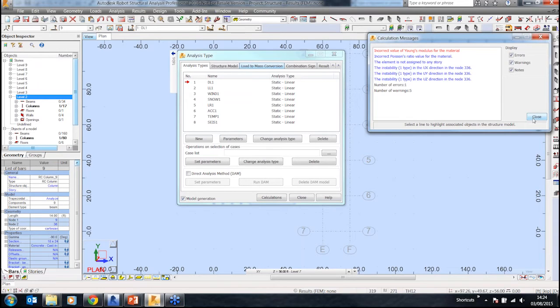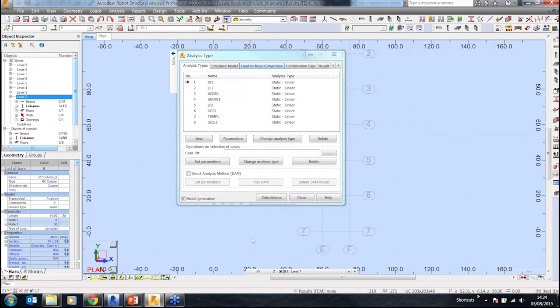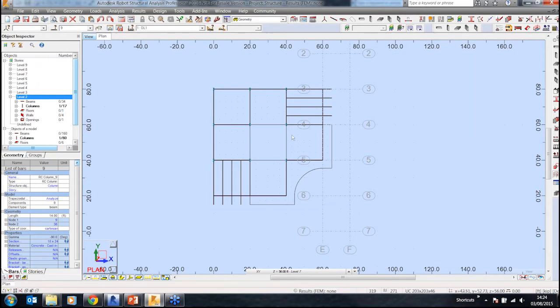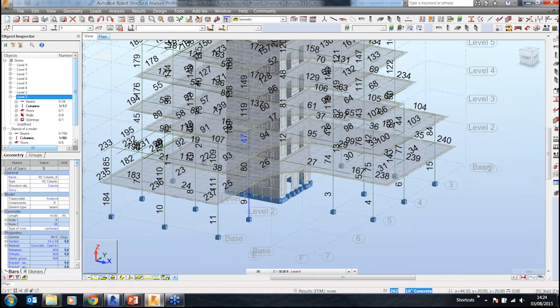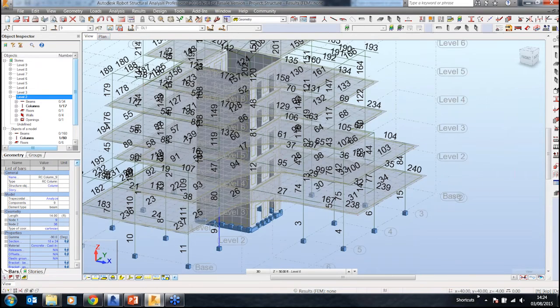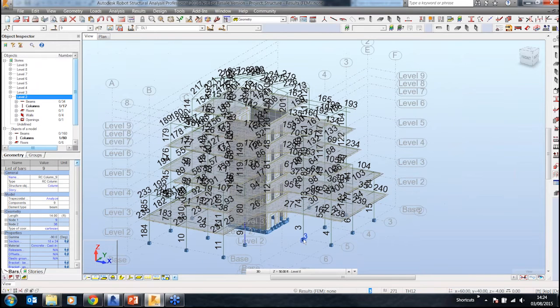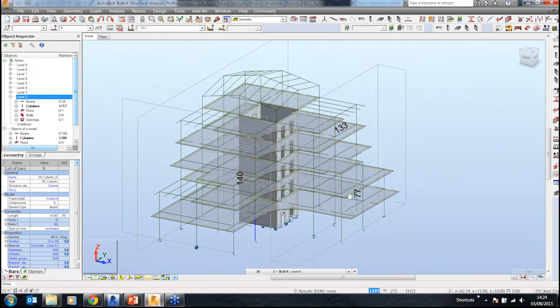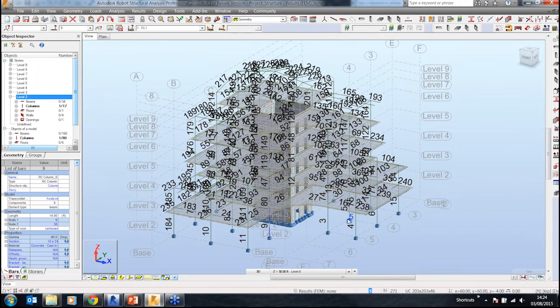One key thing that is a great point to make now is if you're building a model, for example, with this in Revit, you need to make sure that it is a truly buildable model. So, for example, this column here would not be a column that runs from ground all the way up to level 7. It would be split into individual columns as it would be built, as that's how it's going to do the analysis within here.